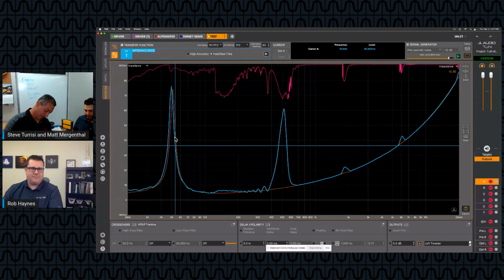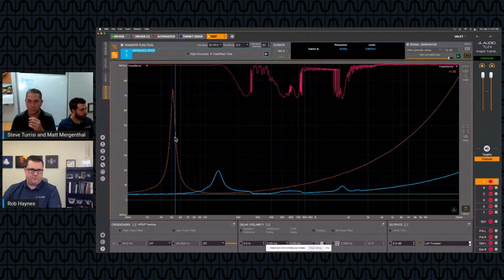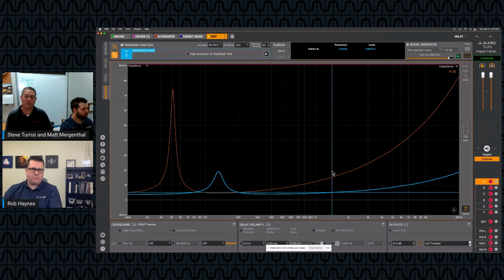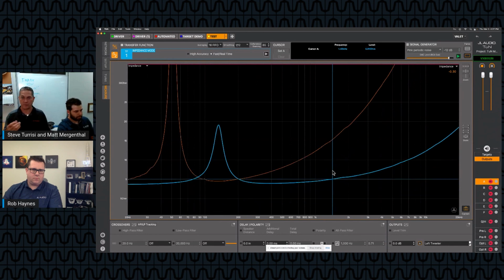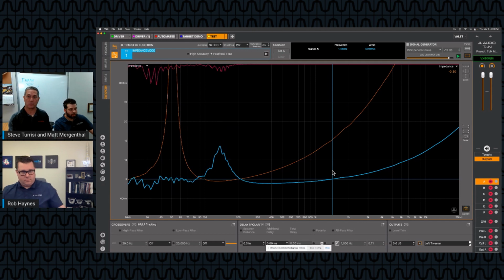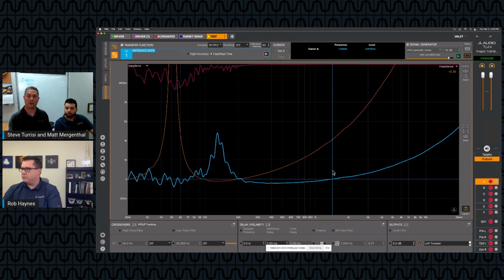And it's not just good for subwoofers. There's other things you could do. We're going to change this guy out, and I'm going to show you. A lot of people are going to be upset about seeing that. It's a C5 mid-range. Yes, we had one laying around. So we're going to connect this guy up. And logically, it's a smaller speaker. So what you're looking at with the peaks on the impedance plot there is the resonance of the driver effectively. So this one has a higher resonance because it's normal anyway for a smaller speaker to have a higher resonance point. So you can see that compared to the other one. Here again, light taps on the speaker cone will cause changes that are pretty dramatic.